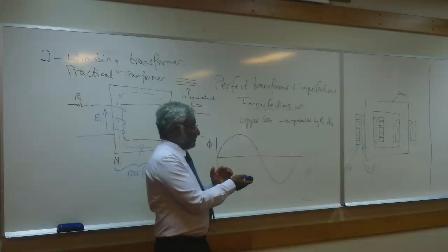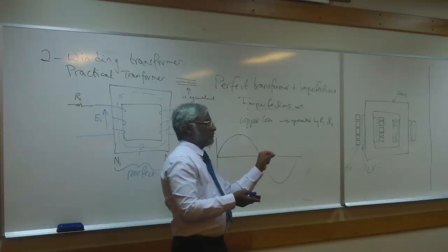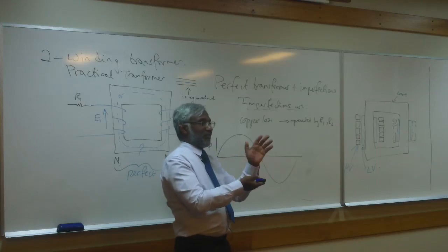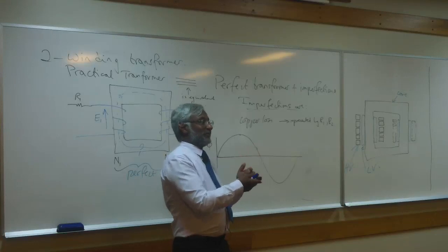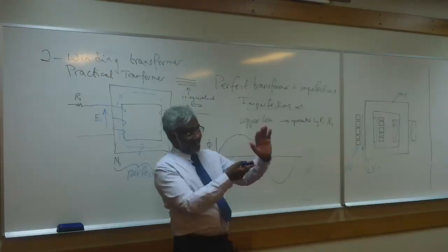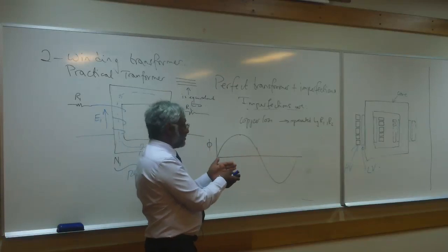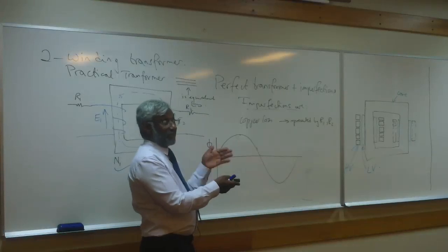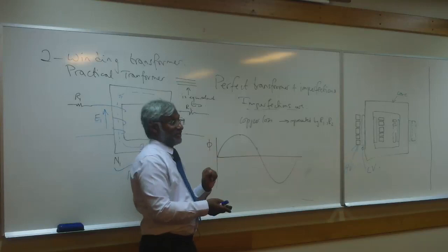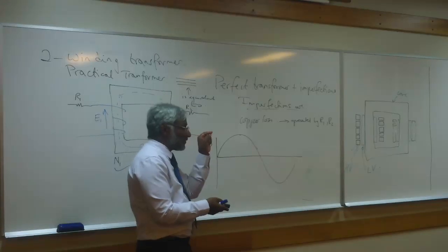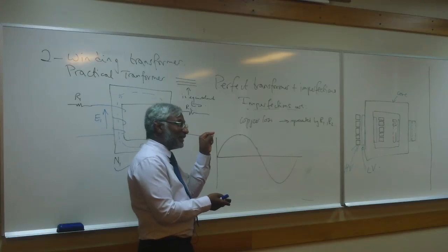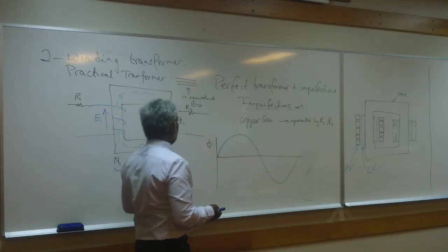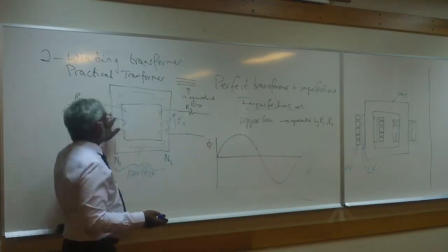Laminations are sheets of a fraction of a millimeter thickness, and they have insulation on them. So don't scratch laminations, because if you do, you will defeat the purpose of laminating. They break the path of the current, so very little eddy current would flow. If you want less eddy current, you would have thinner lamination, because within one thickness of the lamination, you still have little circuits of eddy currents. So we cut down the eddy current by laminating.